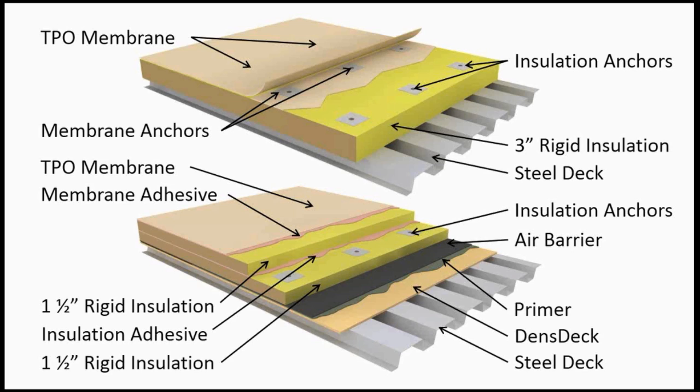We also wanted them to reuse the 3-inch layer of rigid insulation. They actually discarded it. There was really nothing wrong with it, but they had some concerns that there might be mold spores on it. We never really saw any. What we had proposed to do is build tents and actually let it dry out. Again, given the size of this roof, they could have had enough for the one phase and let the other phase dry out while any moisture that was in there. It typically dried out very quickly once they took the roof membrane off.